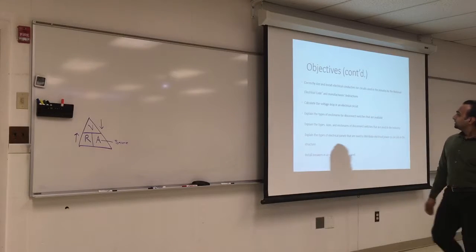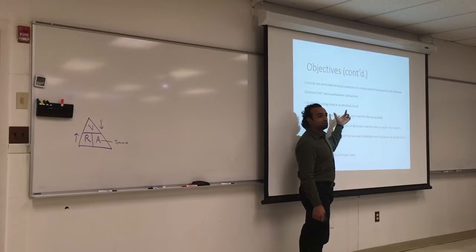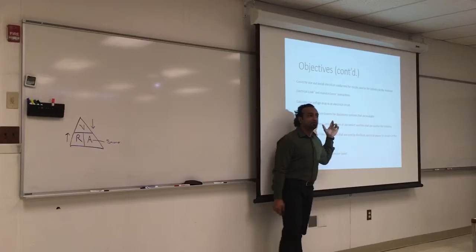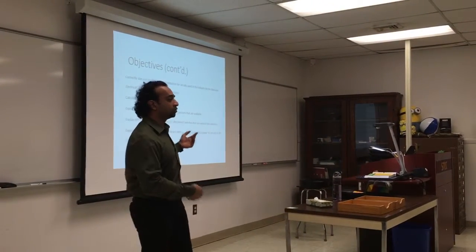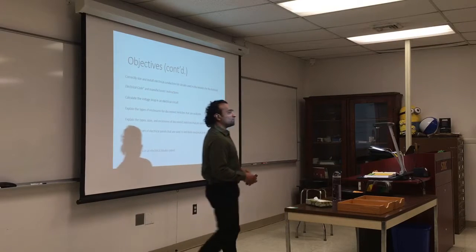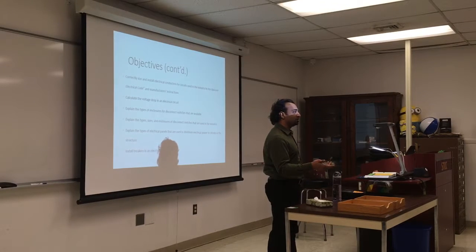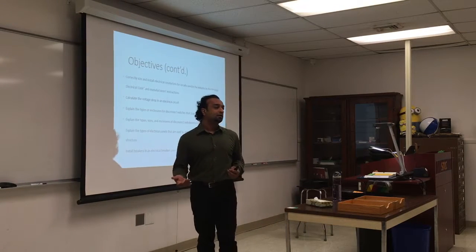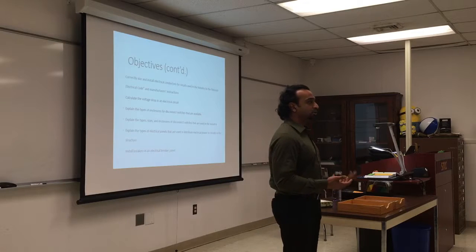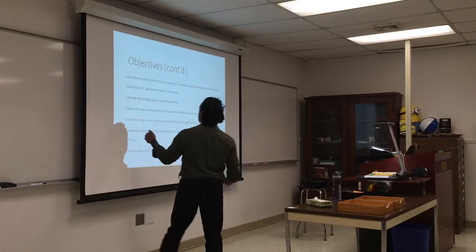Problem solved. So we'll talk about the voltage drop, which is the main reason we're doing all this chapter. Voltage drop is one of the most neglected parts when we do wiring. You can buy a big bundle of wire and just expect voltage to go forever. But again, always go to the water circulation analogy. If you have a long pipe, eventually you'll lose a lot of pressure. So you cannot have infinite pipe and have the pressure stay the same. And if we compare voltage to pressure, then it should be the same. Voltage is not going to be the same for a long distance. It will keep dropping slowly.